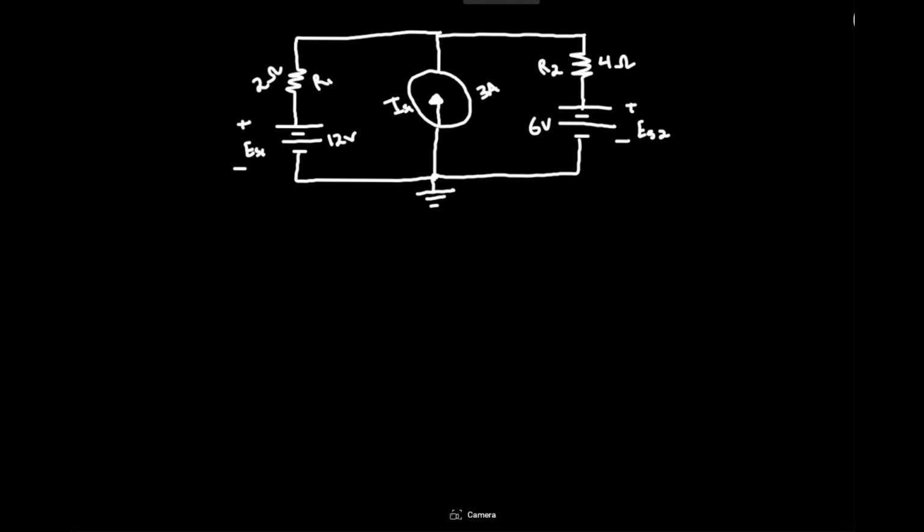Now first thing you need to remember is label everything, and then we'll move on to the second step. Let's just first label everything. Now we need to find the reference point and the voltage node. In this case, we're going to assume that the reference point is the ground, which is easier, which is always 0 volts. So it's connected to this one, this, and this. It's connected to all this, which is going to be 0 volts, which is the reference.